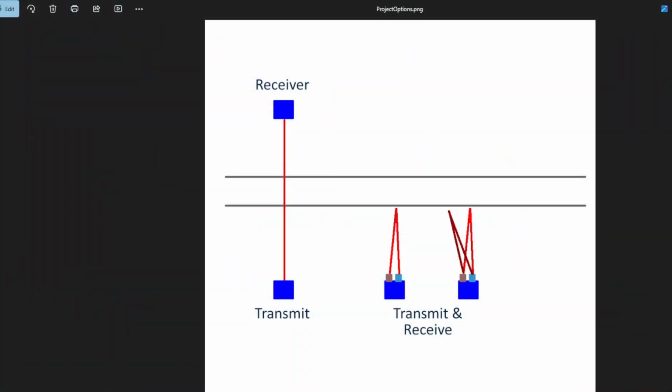So this project was something that someone had asked me to build, and I'll be honest, when I tend to think about timing between 2 points, the ideal system for me would be a beam that goes across the track. This is my track here, and the idea is that the train would break the beam. I would then have a second beam further down the track, and that beam would then be broken. That would be a very, very exact method of, if you like, timing between 2 points.